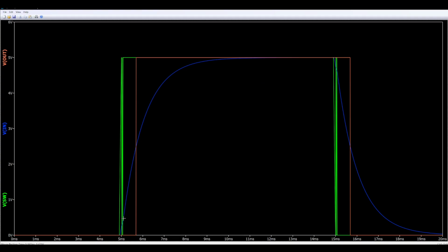So the yellow here that you see is just to represent switch bouncing. Keep in mind, this is in milliseconds. So your finger hits the switch, you get a little bounce here and there. Right here is our RC curve, the blue, if you remember that from previous videos. And then the orange here is our properly debounced switch, as it were.